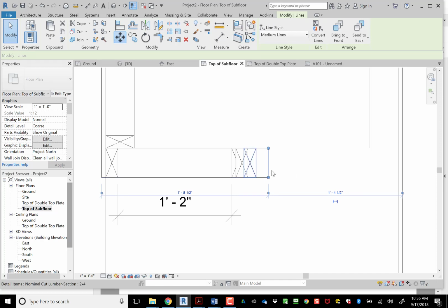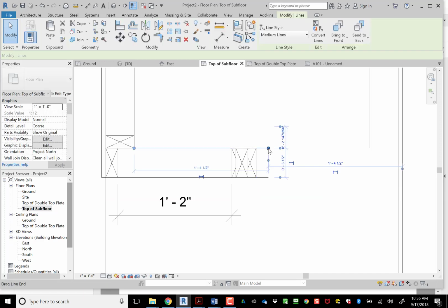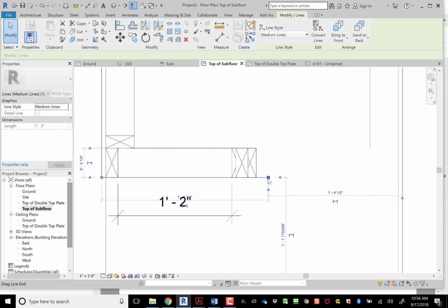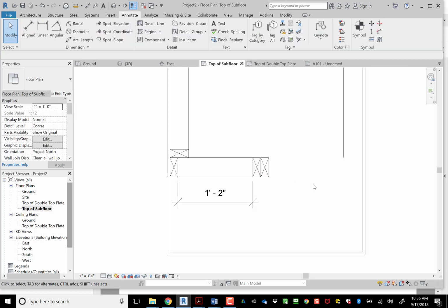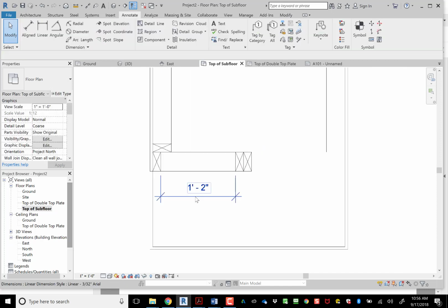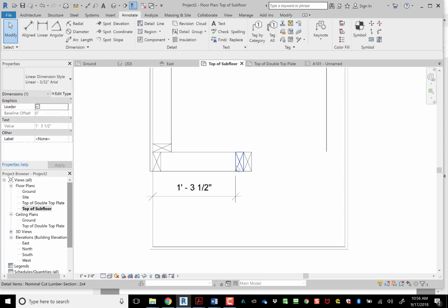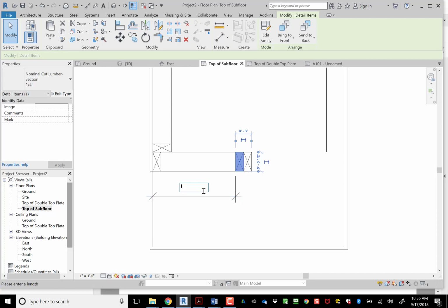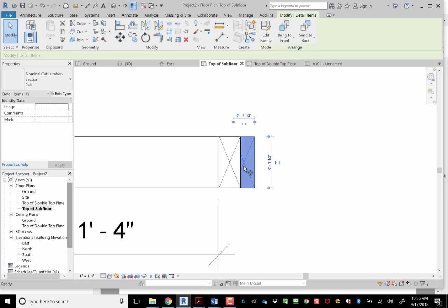Because you're maxed out at 16 inches, you can move your wall in to reflect that. Again, my wall is faked right now with lines, just because I was trying to do it fast. But then that is better. And then this one, just to see that the spacing is correct. Oh, it's still not correct. This should be 16 inches. So this should go over there.